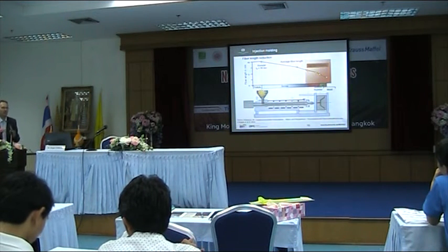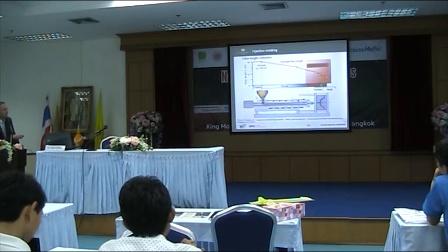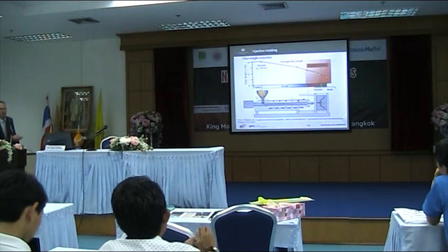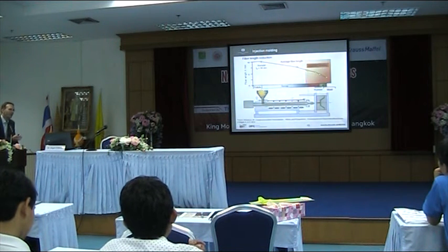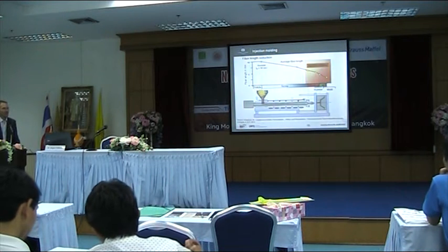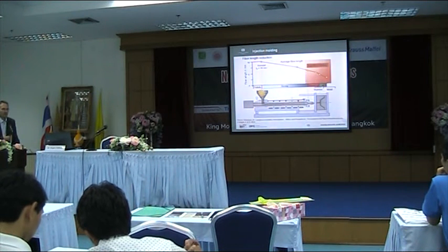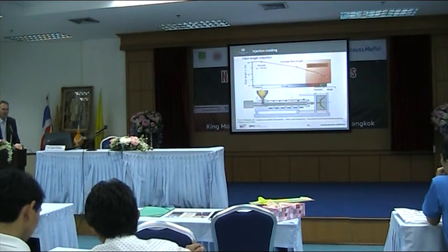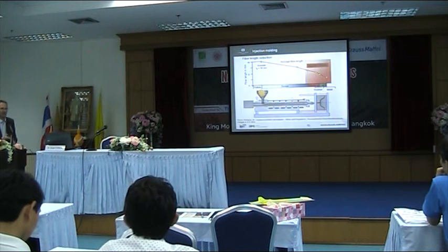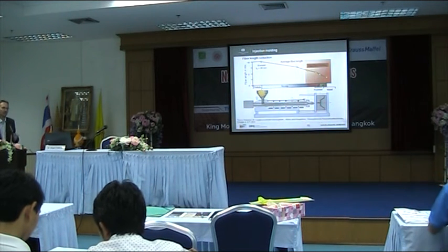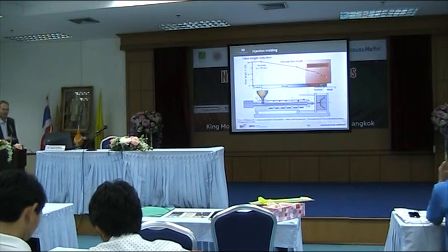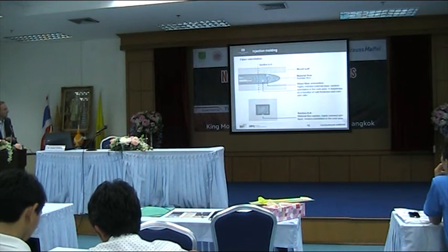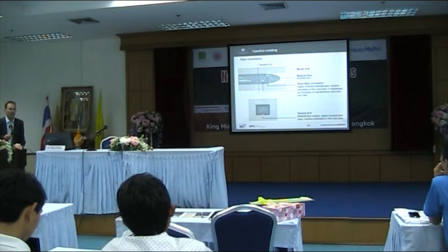If you really have a smooth process, with low shear rates and so on, slowly in injection molding, and you have not so thin walled parts, you can maybe reach 3 to 4, 5 millimeters on average. Some fibers are longer, some shorter, but longer is not possible. Okay? So this is the big disadvantage of injection molding when you use it for fiber reinforcement. But you have to look at the resulting properties, because fiber length is not the only factor.